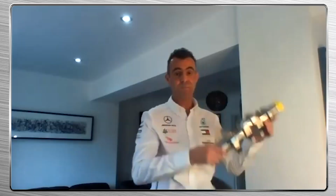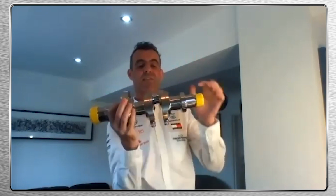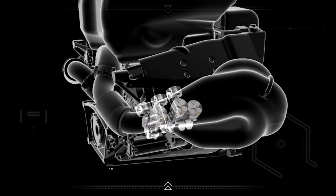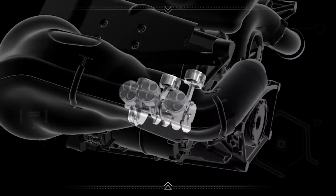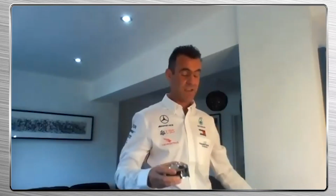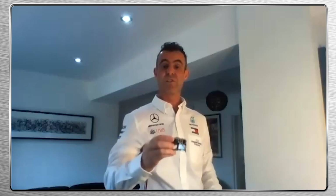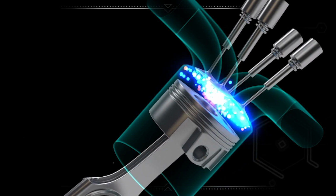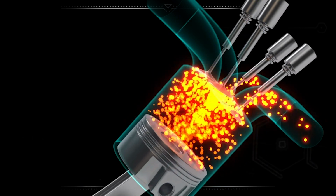I've got a crankshaft here, which is my single-cylinder crankshaft, not from a V6 engine, but from a single-cylinder development engine. What I'm trying to show here is that there's an offset. If I can hold it properly, you can see there's an axis of rotation, and then there's this offset crank pin. We connect from that offset crank pin via a conrod to the piston. The stroke is when the piston moves from the top of the cylinder to the bottom of the cylinder, or from the bottom to the top. A four-stroke cycle is one movement down, up, down and up, and that corresponds to two rotations of the crankshaft.